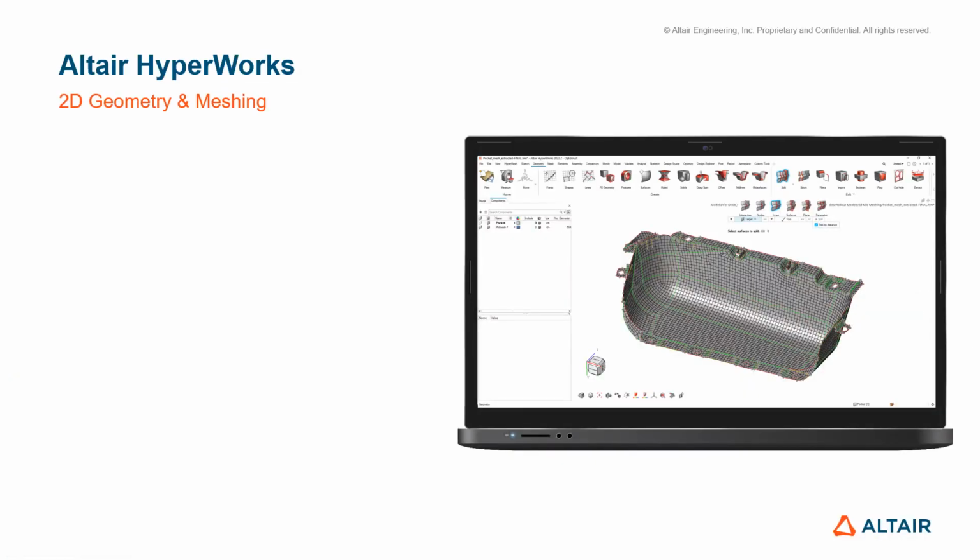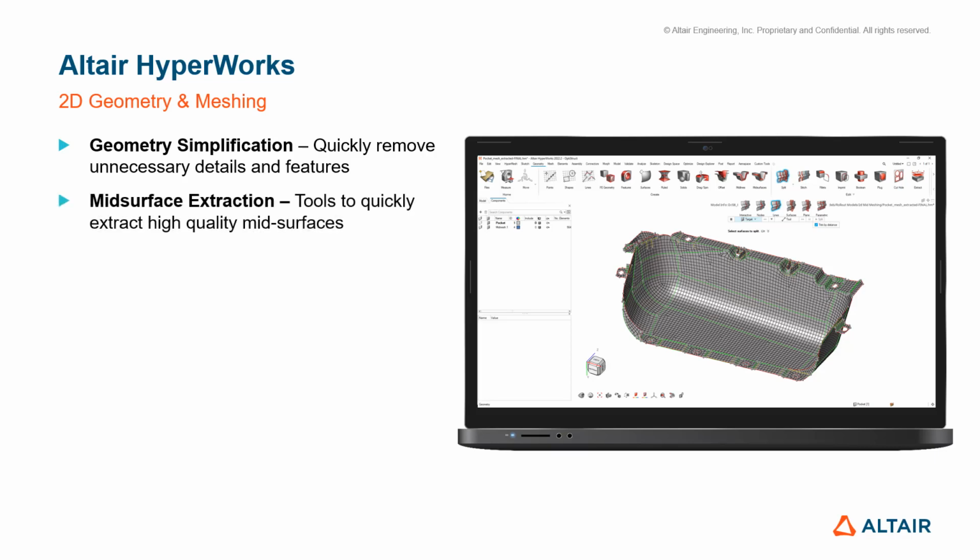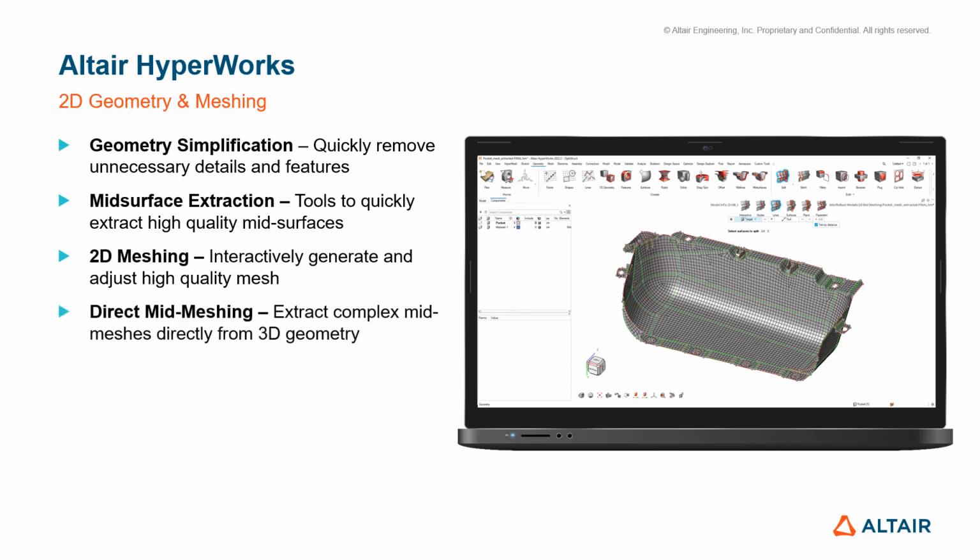So that brings us to the end of this session. We've looked at geometry simplification, so how we can quickly remove unnecessary details and features from the CAD. We extracted our midsurface using the midsurface tools and showed how they could be completely automated with also manual control. We looked at 2D meshing, how we can interactively generate and adjust a high quality mesh. Or for complex geometries, use direct midmeshing to directly extract the mid-plane mesh without the need for the midsurface.